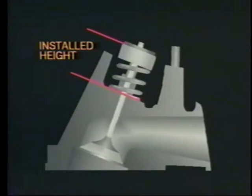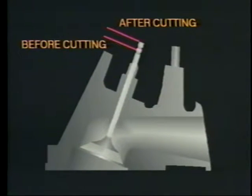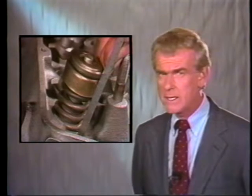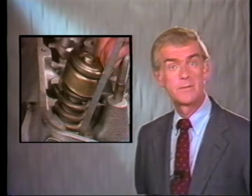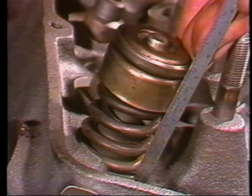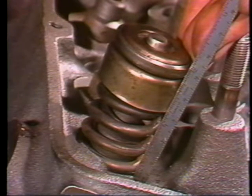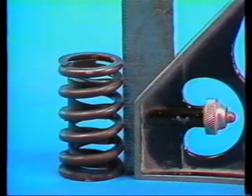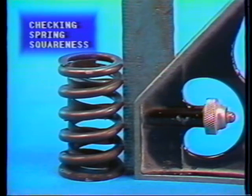Valve spring installed height should also be checked whenever a valve face or seat is cut. The increase in valve stem installed height will increase the valve spring installed height. This will decrease the valve spring tension. Valve springs must be compressed a specified amount to provide proper tension and proper valve function. Valve spring installed height can be checked by measuring the spring's height or length when it's installed on the cylinder head. Spring shims can be used to correct excessive spring height, but don't use shims to compensate for weak springs. Before assembly, the spring should always be checked for squareness and proper tension.